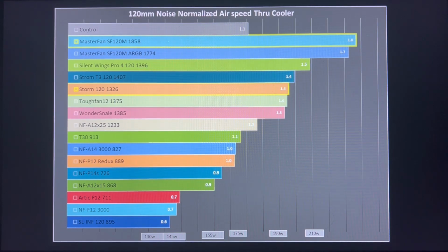A little while ago, I did a whole series of tests and actually published a video on the maximum cooling of my CPU cooler. I used my CPU completely unlocked, letting it go to its thermal throttle limit at 91 degrees C, and just let the CPU run at whatever wattage it could draw maximum for each air speed.